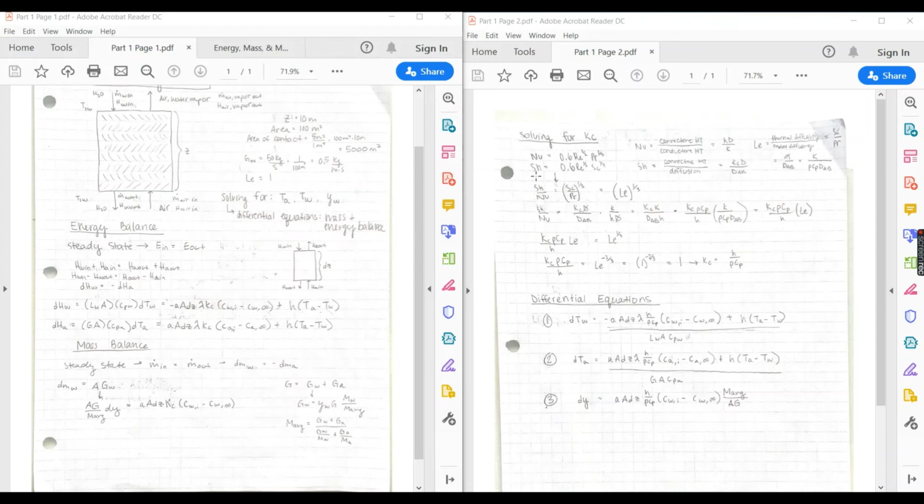So if you put the Sherwood number and the Nusselt number into a ratio, this 0.6 times the Reynolds number to the 1/2, these terms in both of the equations will cancel out. And so if we have the Sherwood number over the Nusselt number, this will end up simplifying to the Schmidt number over the Prandtl number to the 1/3 power.